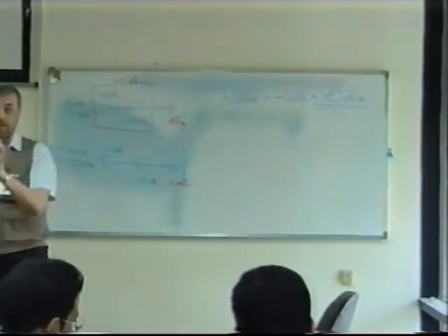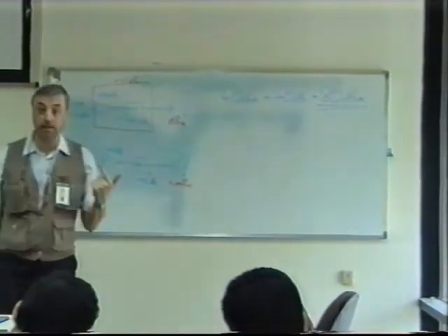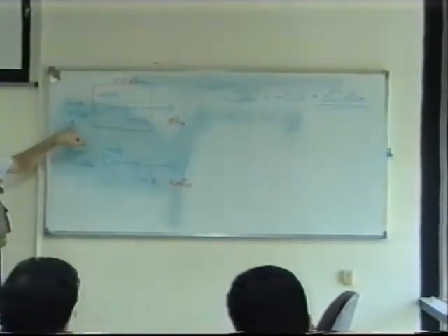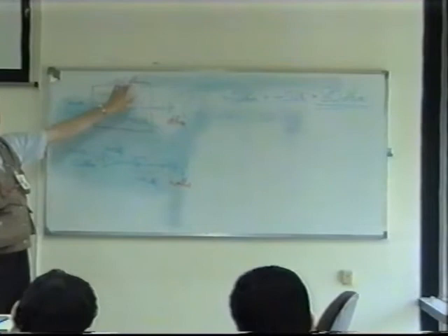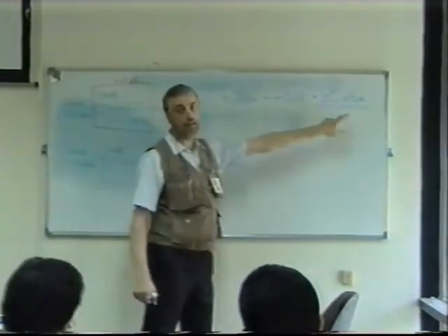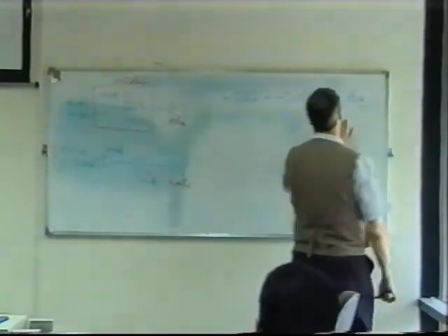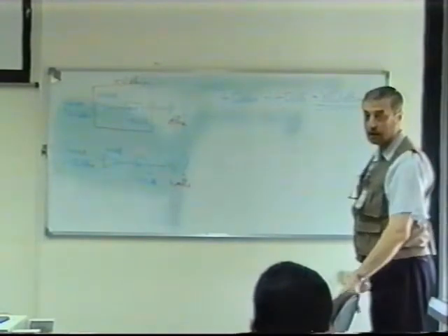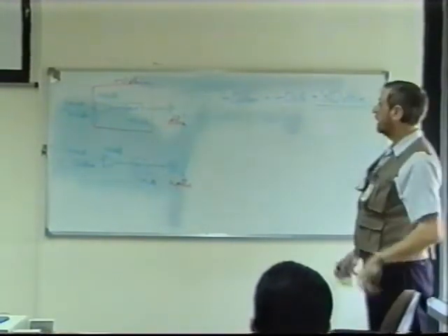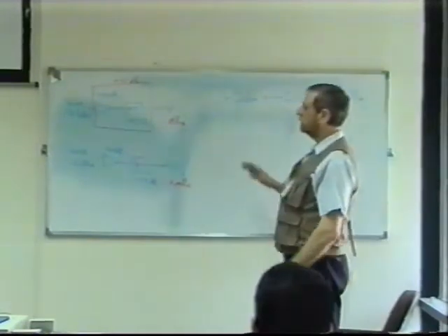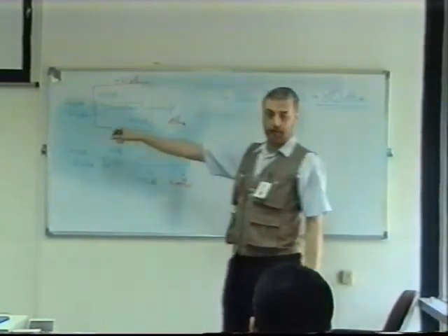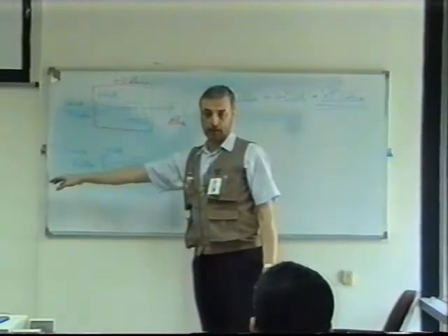That's why we use decibels. And of course, dBm is just decibels relative to 1 milliwatt, isn't it? Yes. So if we have 40 dBm input, we add 40 to it, gives me 80 dBm output. So easy to calculate. If you're going to change this to watts or milliwatts, dBm and dB are not different, but remember that dB is a ratio of power. dBm is a ratio to 1 milliwatt. Okay?